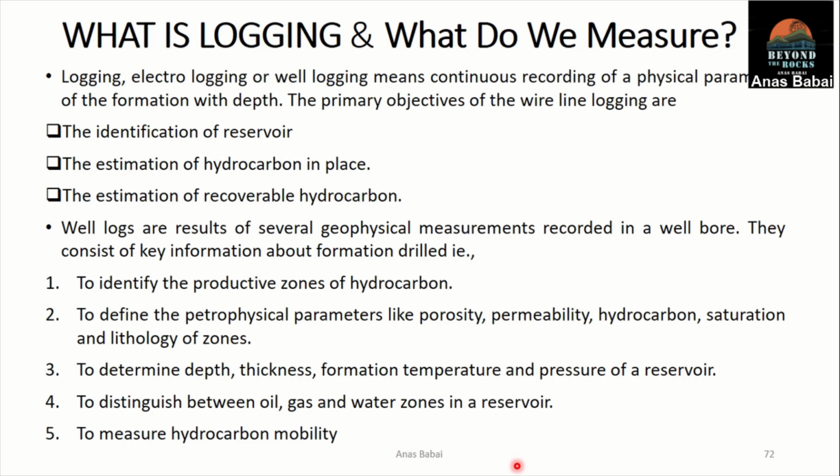And we have seen how we can identify different lithologies in the wells by using the well log, the depth, thickness, formation temperature, pressure of the reservoir, distinguish between oil, gas, and water zones in the reservoir, and measuring the hydrocarbon mobility.